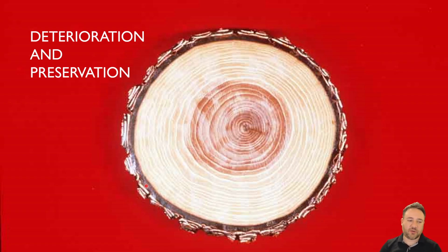Okay, so those are not super important for us to consider because that's all included in the grading process. So at no point are we as engineers basically considering that until we get into the case that we have a piece of timber or lumber that has been installed and then cracks after the fact, and we would like to check what the strength is. In that case, we have to make some assumptions to consider how a split or a check or something affects either the cross-sectional area or the effective length of a section, or how the section will buckle, or what the shear strength of the specimen is.